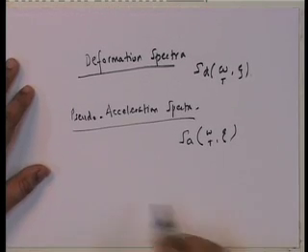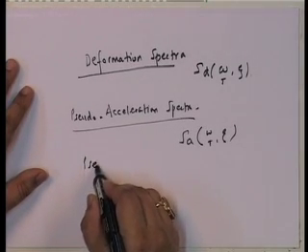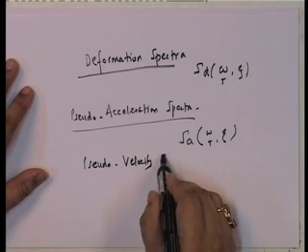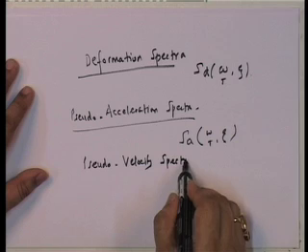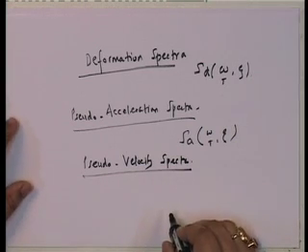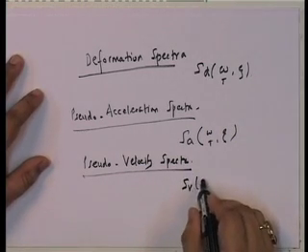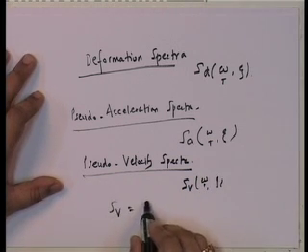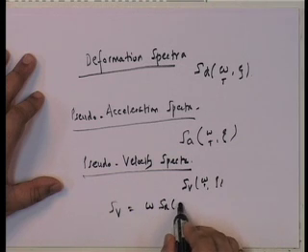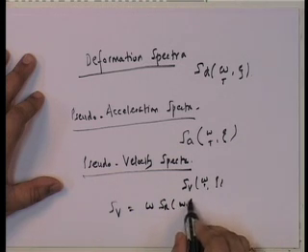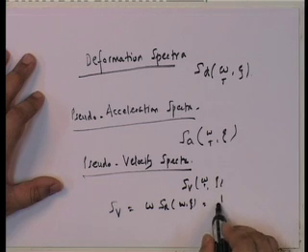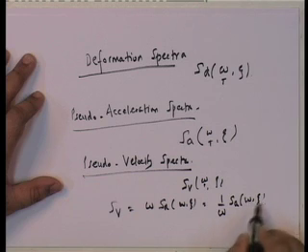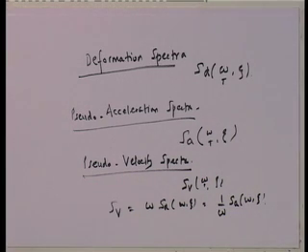And finally, there is the pseudo velocity spectrum. And where does that come from? That is called S v, function of omega or t, and S v is equal to omega S d, which is equal to 1 upon omega S A, okay, because obviously this thing.